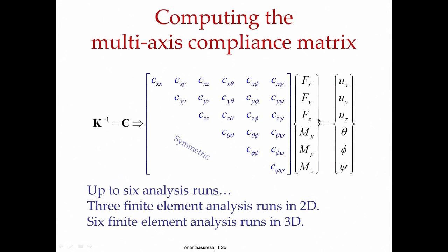If you look at the reverse of it, where I define the inverse of the stiffness matrix as the compliance matrix C, then we can talk about this. Let us say if I want translation along the z axis, then Czz, because it is compliance, has to be very high, and all others have to be 0, because compliance is the opposite of stiffness.